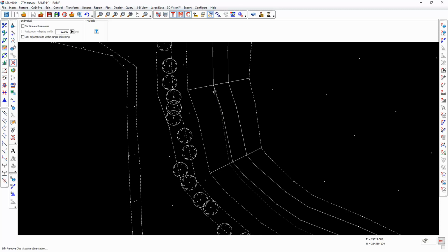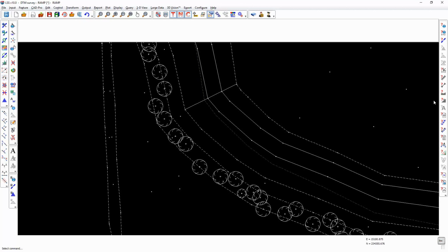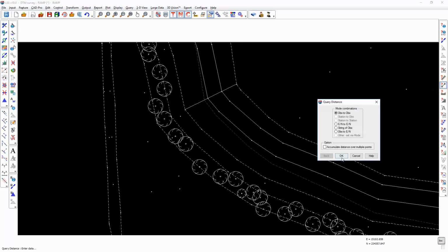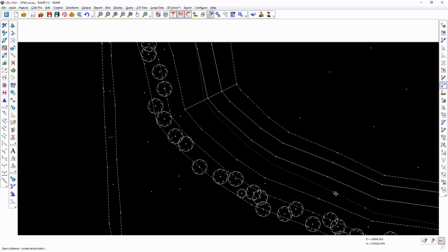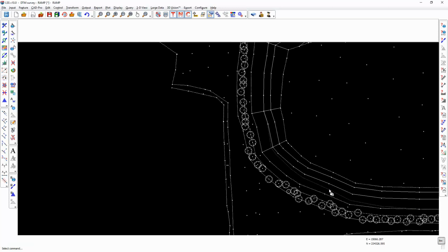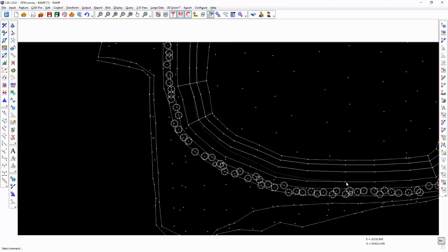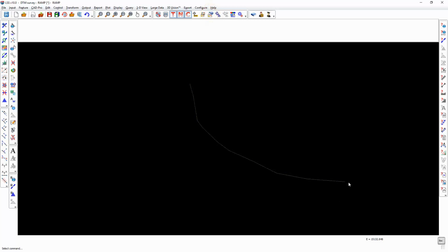Perfect ramp design which intersects with the bench, and this line is running at a 1 in 20 slope down the side of the excavation. You could then use this as the reference line for a template or a sidewall design to create a haul road with safety barriers and intercept slopes with the original quarry excavation survey.